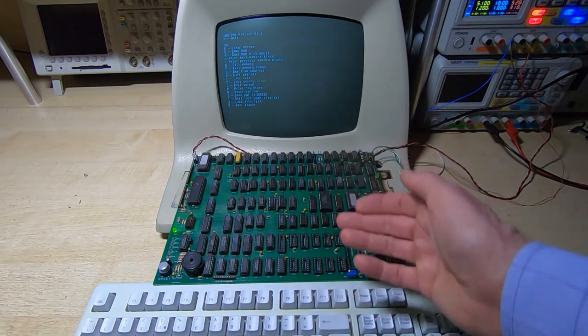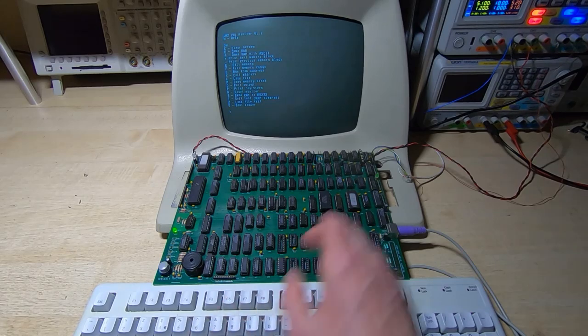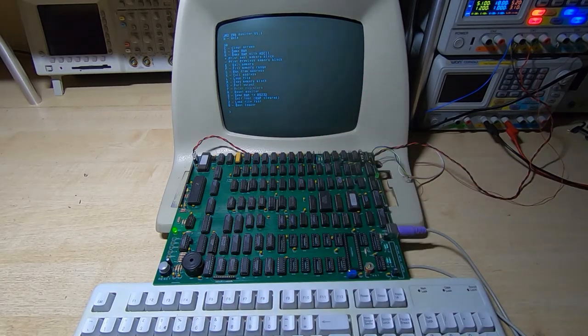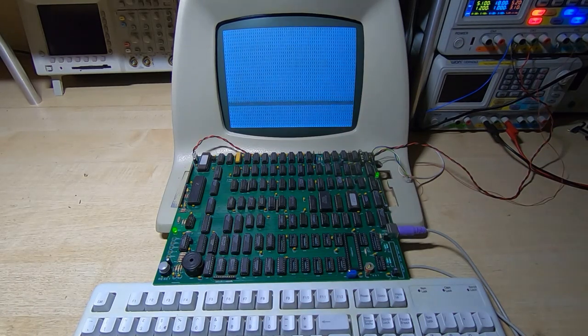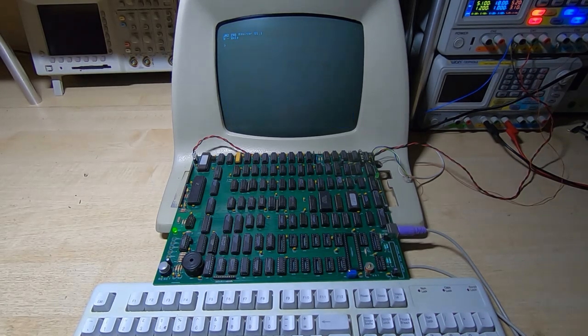And we should now be able to rerun the self-test, and we should see the LED come on. The screen will obviously have a lot of characters on it, as the self-test does include the video SRAM. And that's what we expect to see. That should clear in a few seconds, which it does. So very promising. We'll try dumping the RAM. In fact, we'll try dumping the ROM to start with.